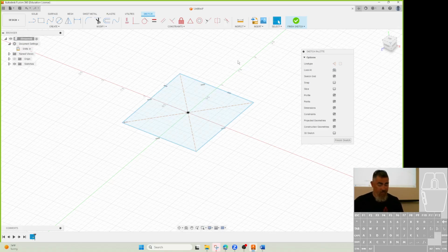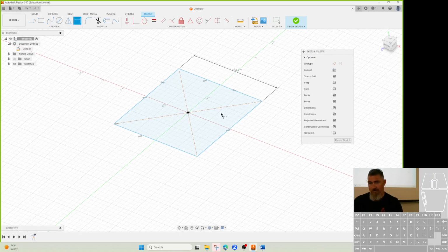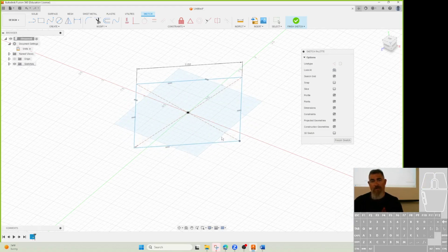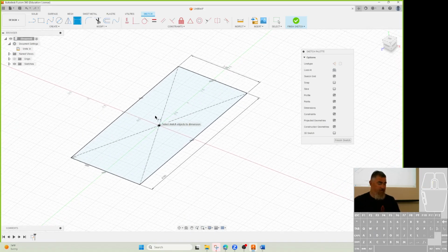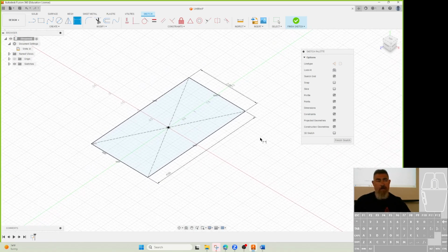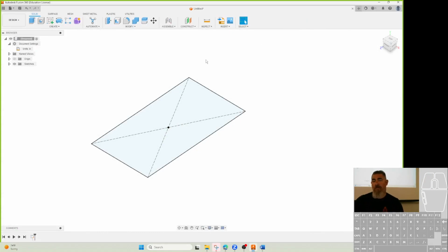All right. So I've got this rectangle drawn. Can I move on now? No. What do I need to do? I need to dimension it. Call it 2. Now it'll turn, so I actually want to erase that equal, and I want to make this horizontal. So I can change that. There we go, there's my sketch. It's all black, so I can move on. I'm going to tell it finish sketch. So it's here, and now I can tell it what to do. I want to extrude it.